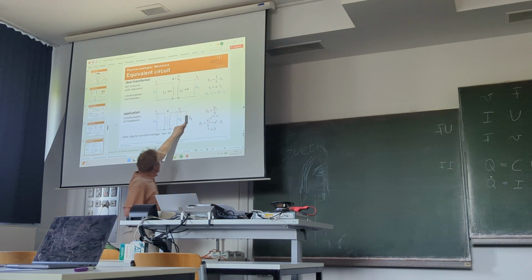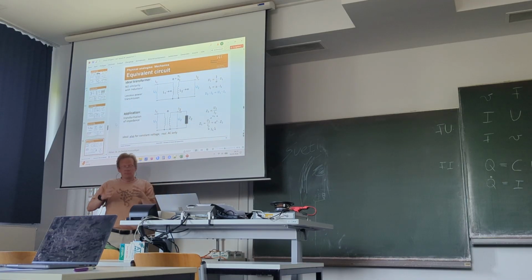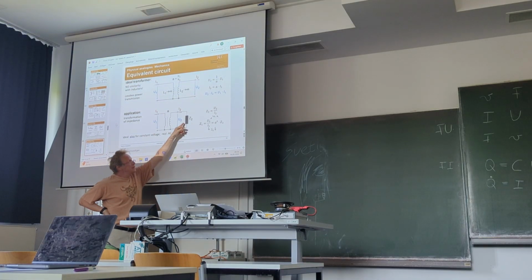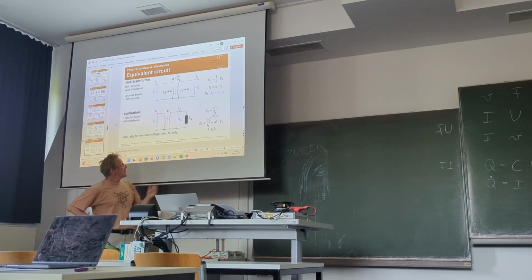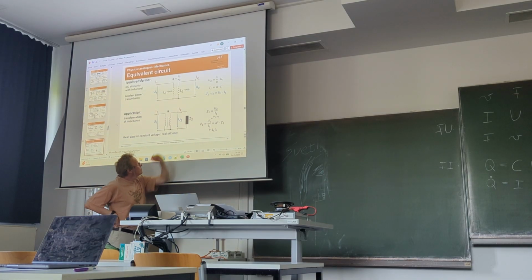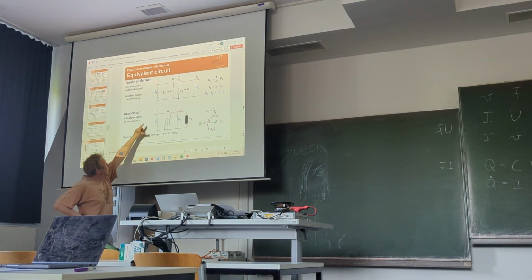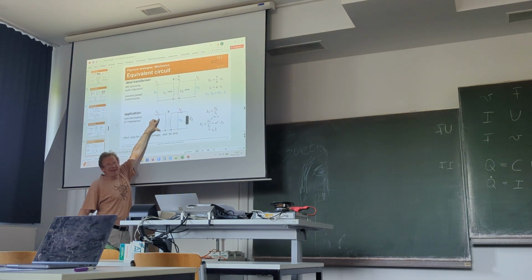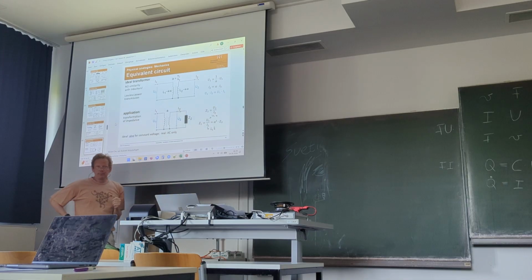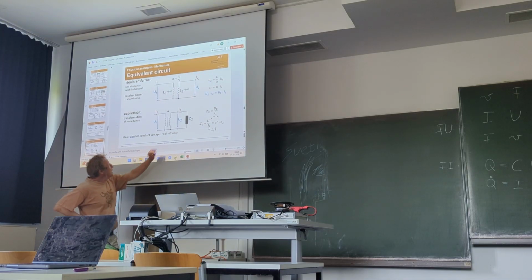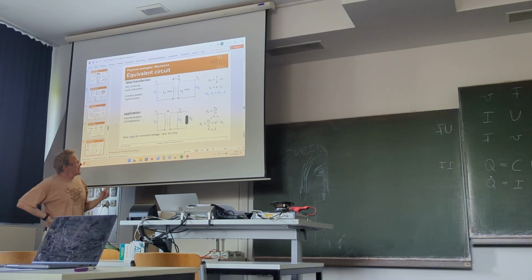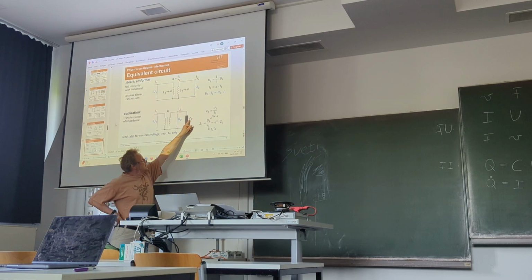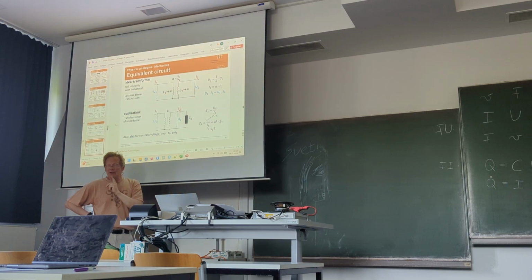What they are doing is they can transform something that is attached to this transformer. So we said, if we have here on the right side any impedance, it could be a resistor, but it could be anything else, called Z2, and I measure on the left side the ratio of mostly AC voltage and AC current, I won't see anything of this transformer. It looks as if I had this Z2, but multiplied with a factor.